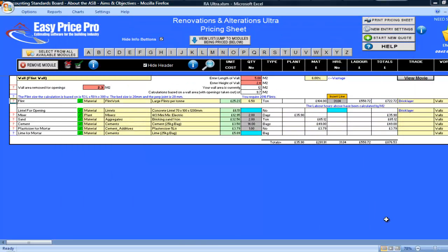As you will recall, I increased the width of my Flint to 300mm. The quantity of Flint that I will require has increased to allow for this. The tonnes of Flint are highlighted yellow too. You may wish to alter it as we cannot know the exact wastage, if for example you're having to go through and pick out snap flints or you're making snap flints.